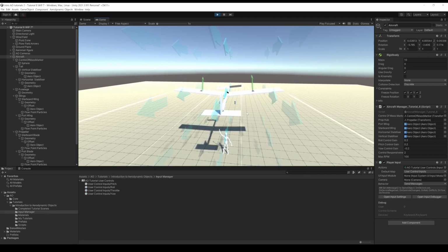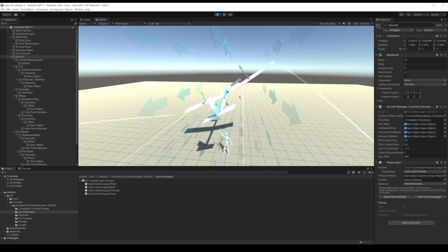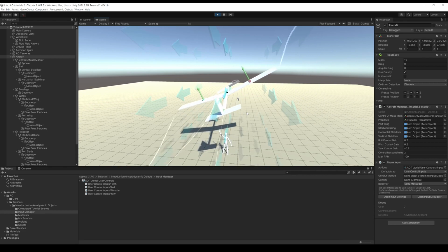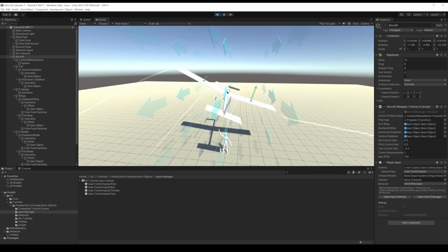I think to remember, when an aircraft is moving dynamically, you've got damping forces on the wings as well, so the lift depends not only on the camber of the surface, but when it starts rotating round, that changes the angle of attack of the wing as well, and that introduces damping. So you can see it's reasonably complicated depending on what the aircraft is doing, whether it's accelerating or not.